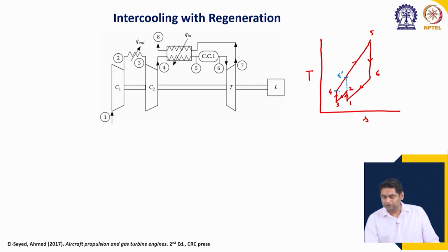This means that the difference of temperature between the compressor outlet temperature and the turbine exhaust temperature is considerably increased when the intercooler is added.